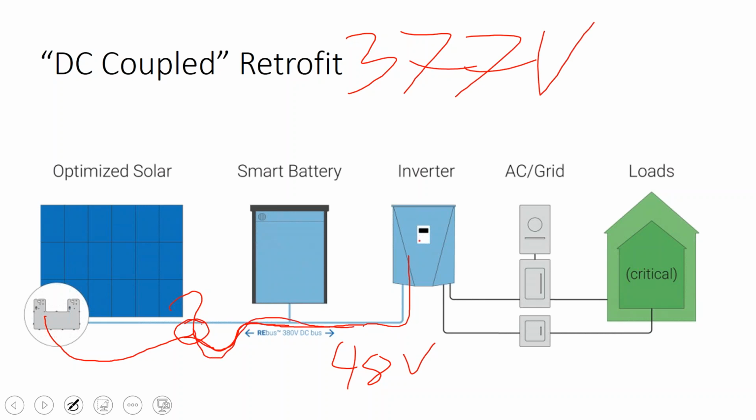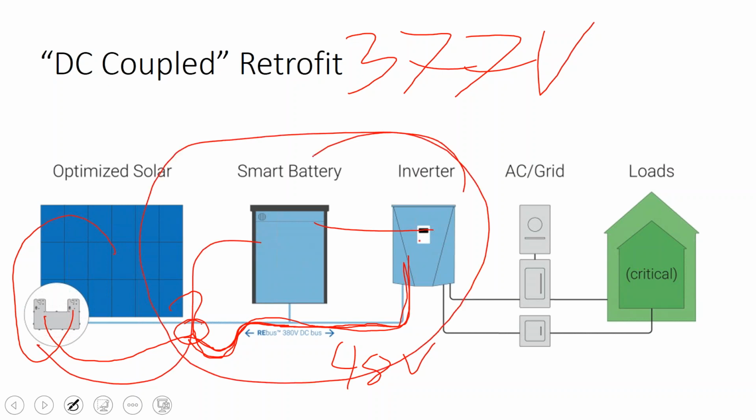But the point is, in DC coupling, you actually have a DC bus bar and a DC service panel with a DC bus, and you're landing the battery bank and the charge controller and solar array onto the same DC bus. It's a little confusing because if you're doing a small off-grid system, you might just go from the array directly to the charge controller, directly to the battery, and then directly to the inverter. And you might not realize that what you're creating is a DC bus at that level. But once you start to expand the systems, you have multiple charge controllers, multiple solar arrays, multiple battery banks, multiple inverters. They're all going to be tied into a DC service panel.